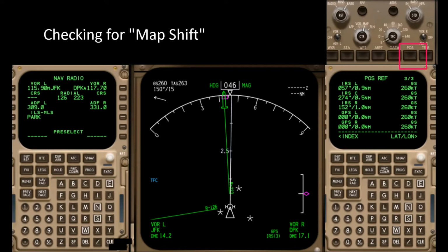The little circle with the 2 ears around it is the GPS position, and the FMC will prefer that, and hence it's right on the top of our triangle. To make sure the FMC is in the right place, you compare the radials and distances that it's showing on the nav display, and I'll just zoom it out a bit.